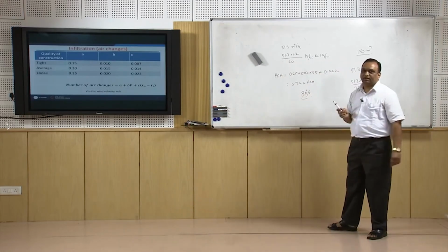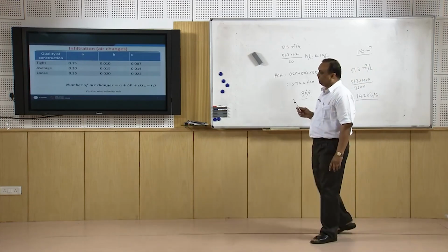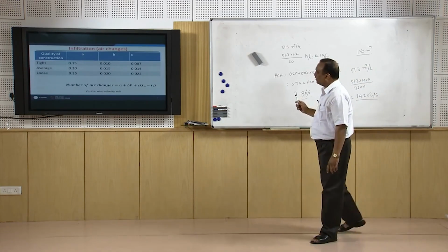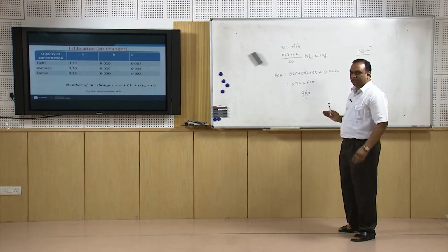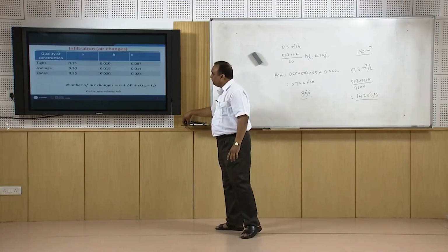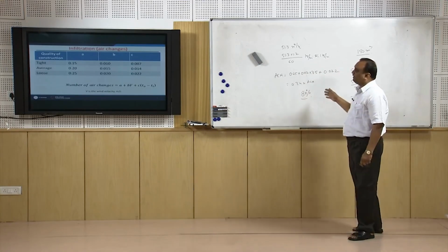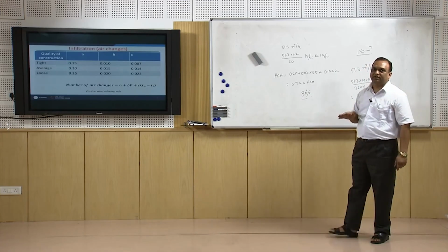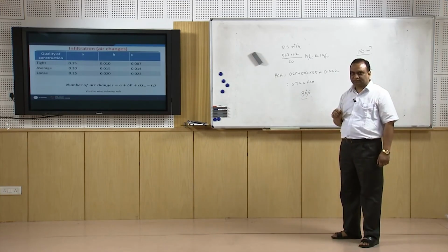So infiltration brings load on the cooling coil, and this causes unnecessary expenditure of energy in cooling the air. So infiltration is an undesired phenomenon in a building. It cannot be completely avoided, but it can be reduced to a certain extent so that the cooling load on the cooling coil is minimum.